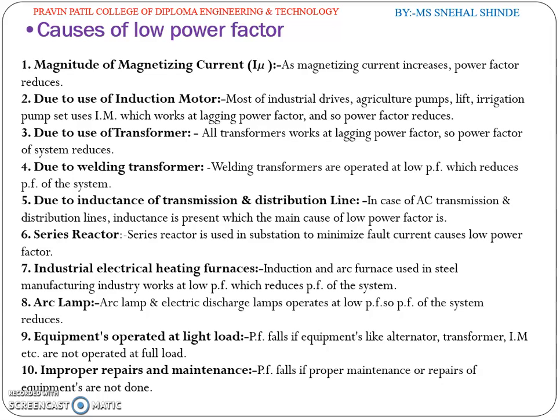In case of worn out bearings, the rotor may catch at the stator. So some metal is sometimes removed from the rotor by turning instead of replacing the defective bearings. In doing so, the length of the air gap between stator and rotor increases, due to which a greater magnetizing current I mu is required, and therefore power factor drops.